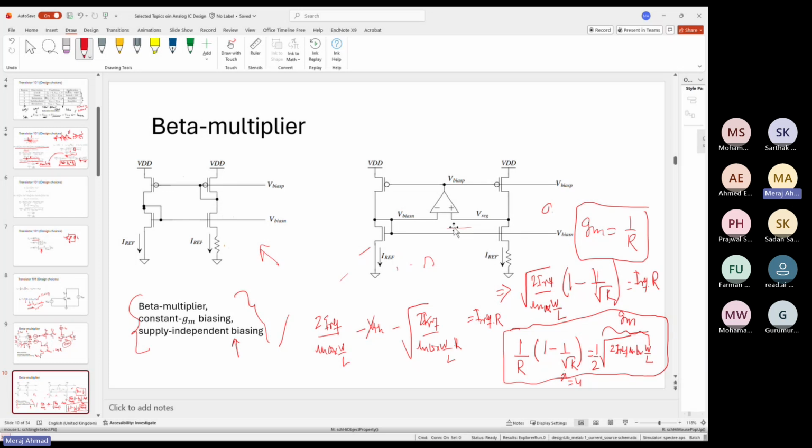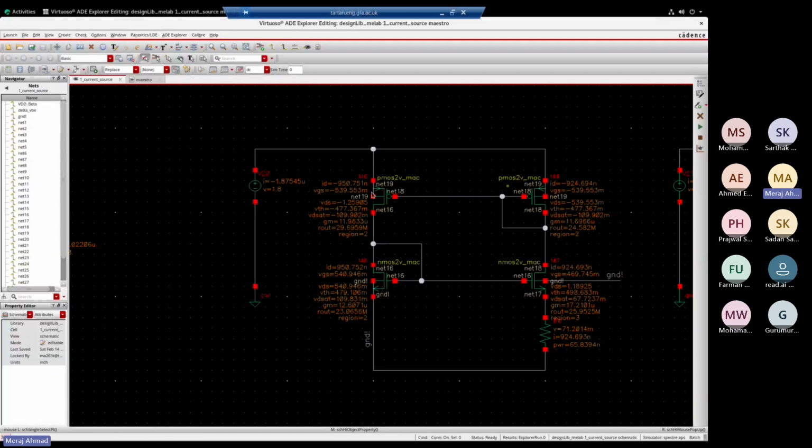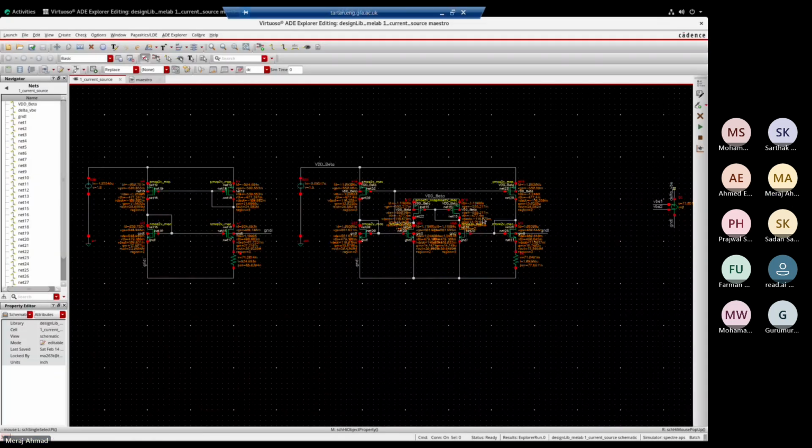So in this case, how we go ahead is we take two transistors. So this is our 5 transistor OTA, but we are not using the tail current intentionally. It will be a chicken and egg problem: if you use a current source in your beta multiplier, then for that you need a reference that will generate that current source.